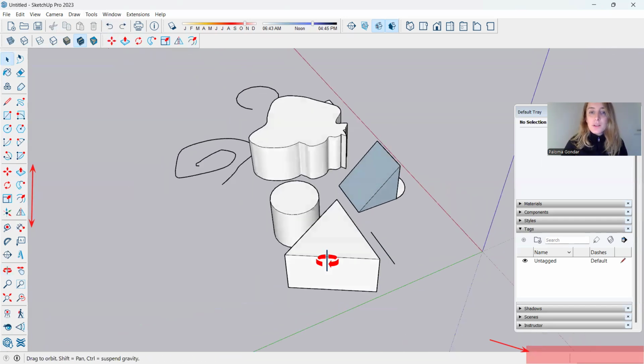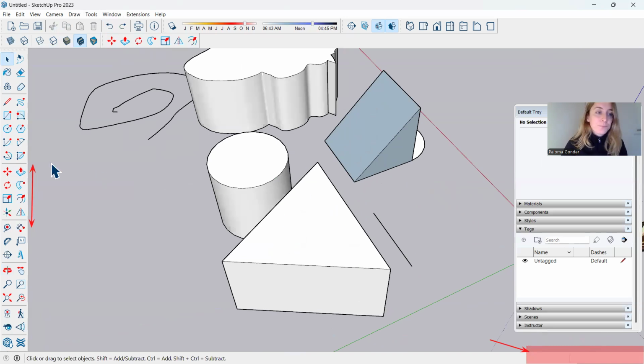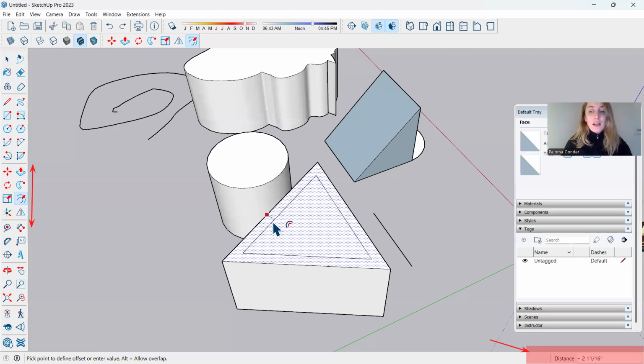Another thing, supposedly I want a wall here. I'm gonna use offset. Did you notice that now the surface is highlighted? Here's the surface, not the lines, but I want the surface. So I'm gonna move my mouse until I check that the surface is highlighted, one left click of the mouse, and then I can put, for example, 2 inches.